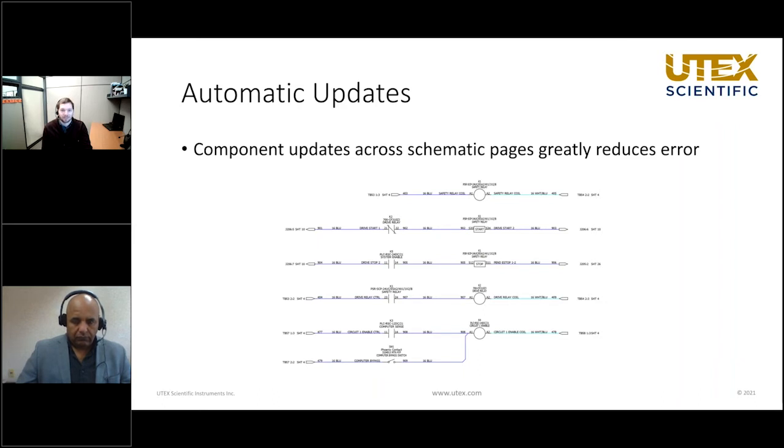Once we associate the symbol as the same component, we really don't ever have to worry about whether those parts will remain connected. We can change things like the component tag number or even change the part completely on one symbol, and everything will be updated accordingly without any manual intervention. When symbols are made correctly, it also allows terminal numbers to be updated correctly. Let's say the original relay had a normally open contact that was 11 and 14, but the new part had its contact as 43 and 44. The symbol will update with this information without me doing anything.